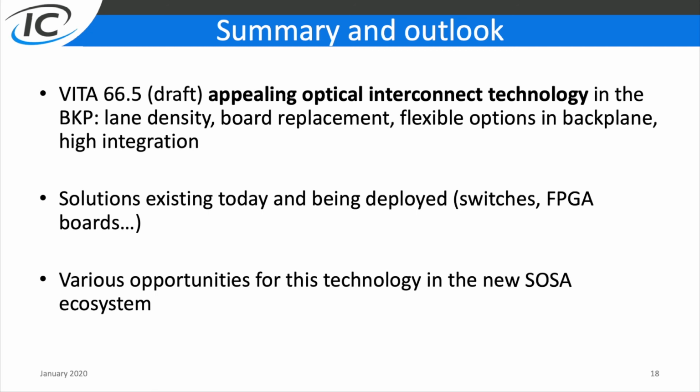VITA 66.5 offers some flexible options in the backplane, and also the ability to combine in the same connector optical and RF connectors. And it supports high-density VPX boards that can be easily customized.